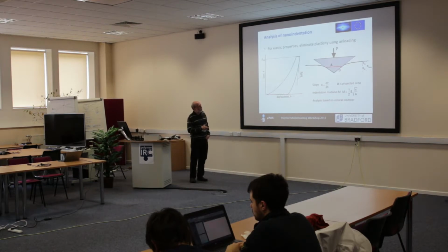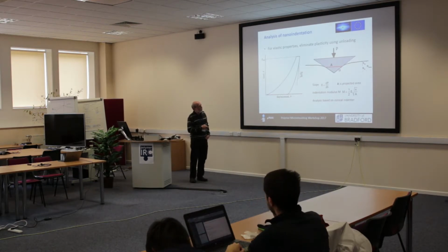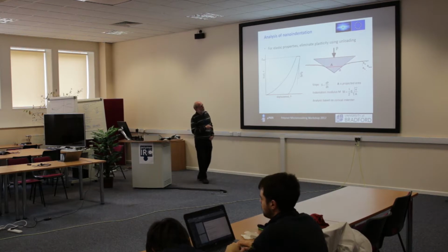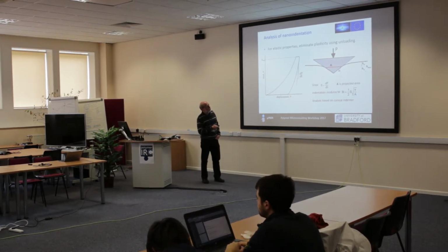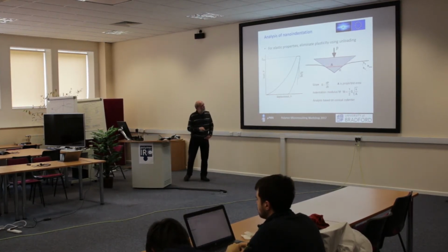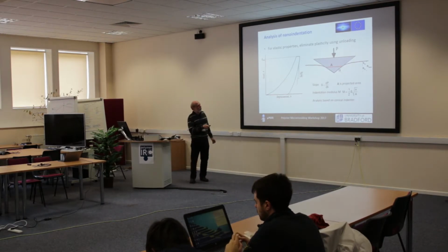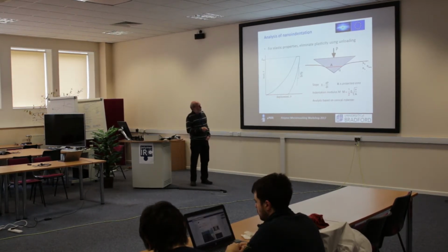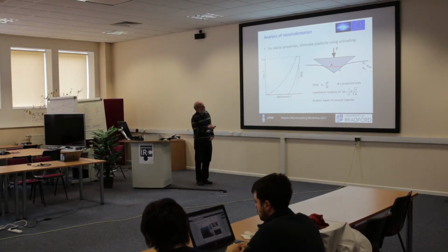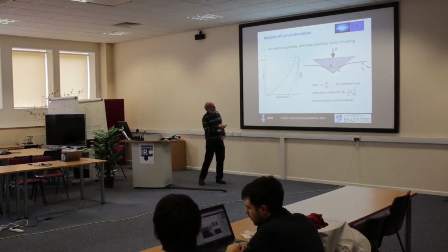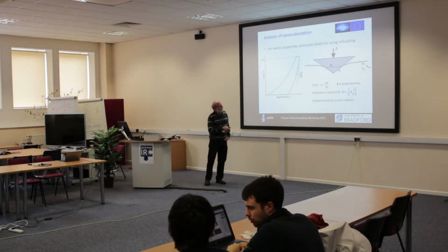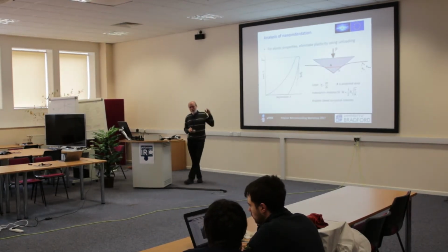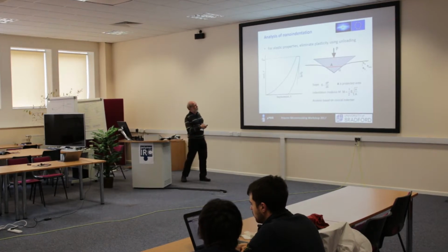And that's the projected area. It's basically, if this was a conical indenter, this area here would be a circle. The red line is the Berkovich. It's going to be a triangle. It's that area. Also involved, and this form is just the area that's involved, but by implication that also involves the penetration depth, which is this depth HC, which is not the same as how far you've driven the indenter H because the surface deflects.